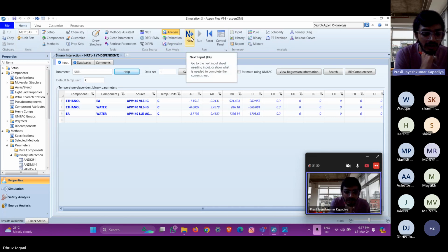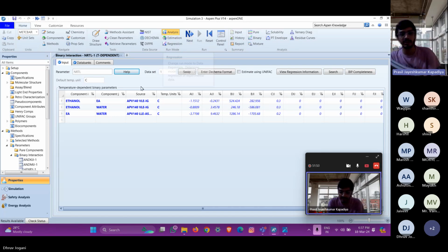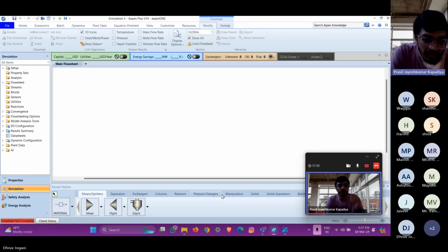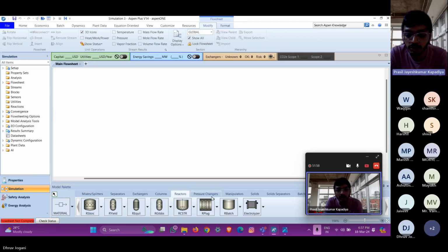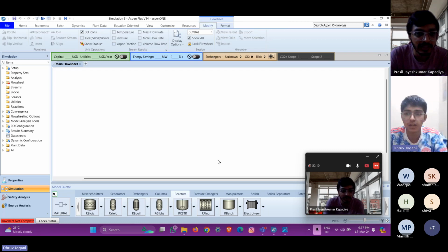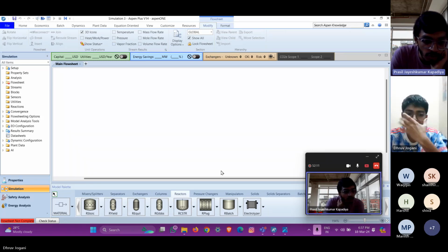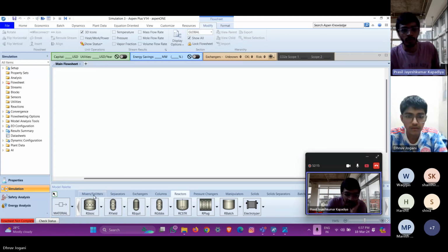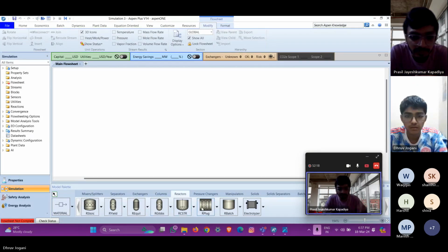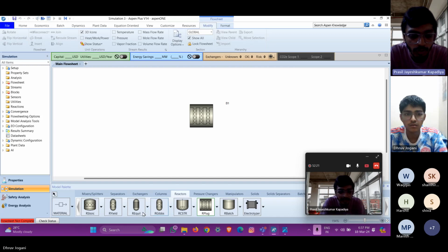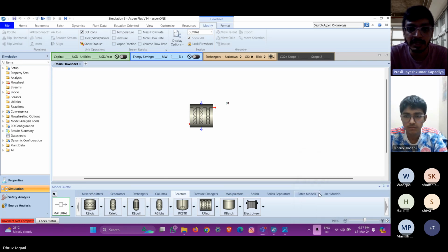Now let's go to the simulation window and create our flow sheet. What you are supposed to do here is simulate one problem using four different reactor models, right? So Dhruv, can you first show your video? Okay, first go to the reactor. Let's go to RPFR first. Choose RPFR. We will use four different reactor models, and we will compare those four results at one time.